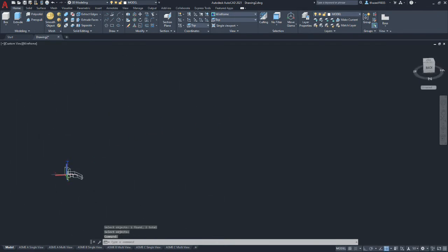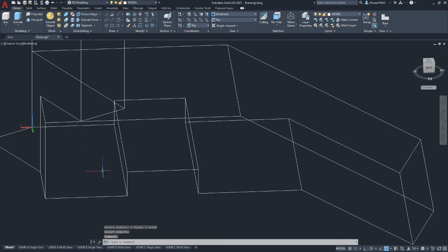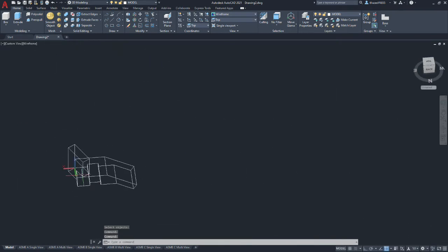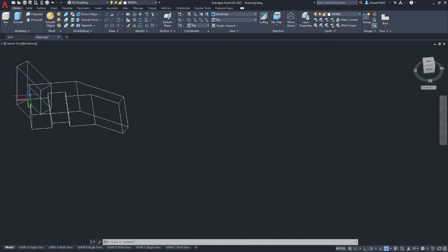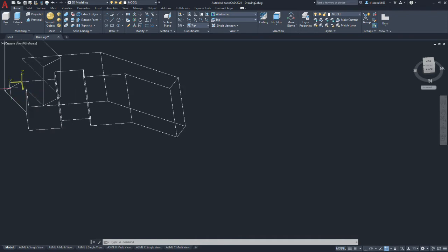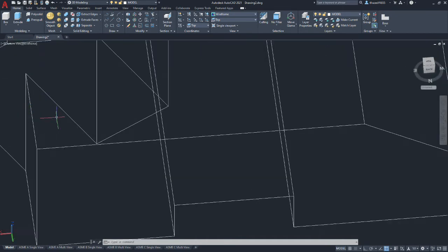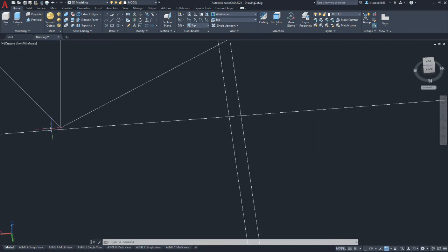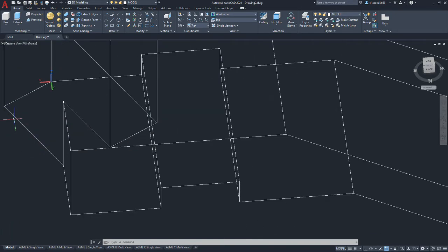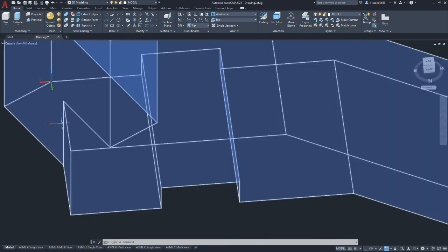Now what we need to do is cut off this triangular section that's in the back. It doesn't show it in the drawing, but I believe it would make sense if this is a surface that a keyway is going to sit on, that this should be flat. Now, if we zoom way in, we notice there's a little gap here. So we need to develop a triangle. We can't just use straight press pull because we need to close up that region.